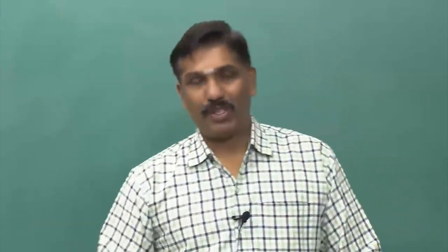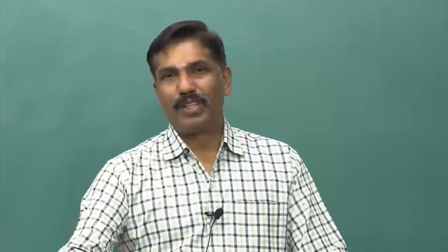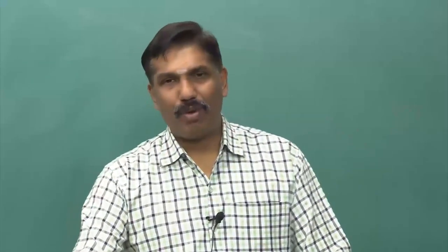The value of the product is also very important. The value of the product is the performance. For example, if you want a single piece, or a single shaft, to be made, then you try to do it by casting, and when you want to do 10, you try to do it by machining, and when you want to do 1000, you do it by metal forming operations.